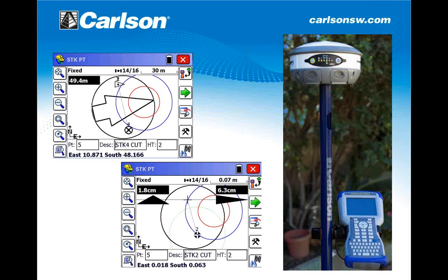It is from the time you are hundreds of meters or kilometers or 10 meters away from the point, and we split the stakeout in a second phase, that is when you get into what we call a proximity circle, and we change the interface to show us, as in the second screen capture below, a more refined guidance to go back and forth, or left and right, to approach the point and make the best match possible to the point.